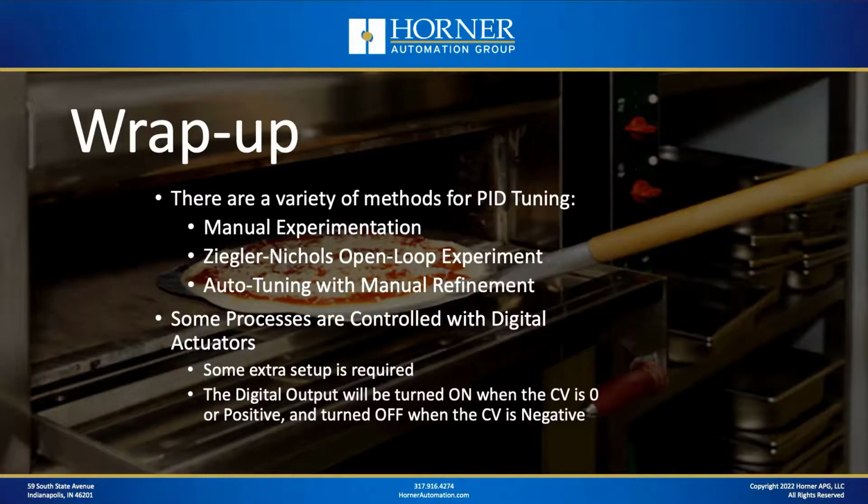Okay, so I think the most important thing about that video, if nothing else, was it shows you the process that you go through when you are tuning a PID loop. You know, if you're starting with an auto tune, getting through the auto tune, getting to the point where you're making manual adjustments, checking to see how those are doing, and then taking it from there until you're satisfied with the results. Okay, so hopefully you found some value in that.